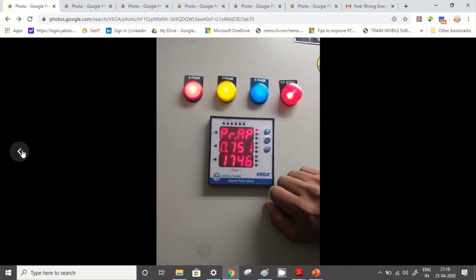But the DG is in switched off condition, so even if you completed everything for the DG, as DG power is off and the DG meter is off, you will not get DG data. So you will get an alarm that ACEM2, AC energy meter 2, communication fail. That is okay. You can verify by switching off the EB and switching on the DG, taking the site on DG, and then similarly you can verify that meter also.